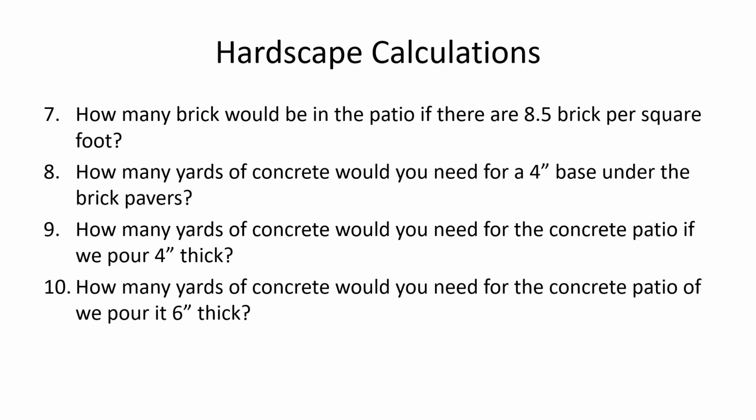And then question 7, how many brick would be in the patio if there are 8.5 brick per square foot? And then 8, how many yards of concrete would you need for a 4-inch base under the brick pavers? Remember, I said I like to have concrete underneath my brick pavers. And then 10, how many yards of concrete would you need for the concrete patio if we poured it 4 inches thick? And then how many yards of concrete would you need for the concrete patio if we pour it 6 inches thick? So again, you've got the 10 questions that you're going to answer for this course.